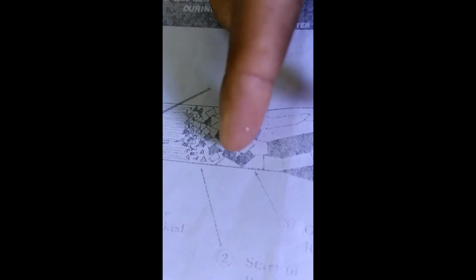Here it is clearly written. So this is your heat affected zone. So basically if you see the structure, here in this area you can see the grain sizes are larger, then slightly it is reducing and going smaller and smaller, and then the base metal, and this side also the welded zone, and this is the heat affected zone area.